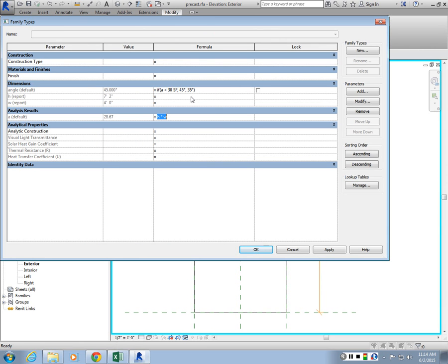Now I could keep customizing this. I could basically come in here and replace the 35 degrees, so when A is not smaller than 30, that means A is going to be greater than 30. The area, the panel is going to be really big. Maybe we want to use smaller angles, right? So I could do if A is greater than 50, use 10, else use 25, and close it. So that's a nested if statement I placed there. I could do one for here as well.